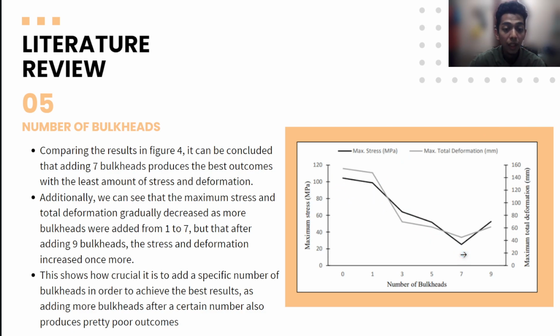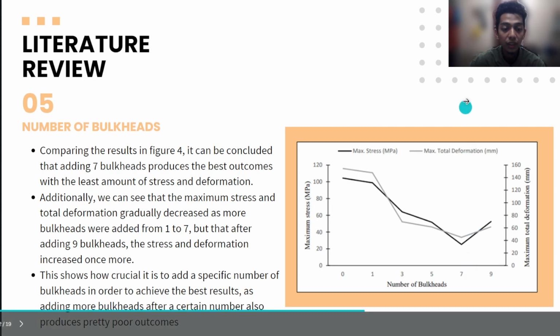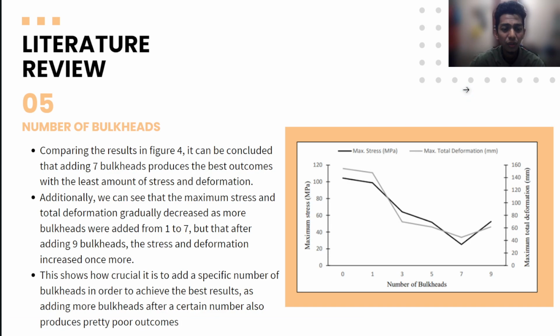But after adding 9 bulkheads, the stress and deformation increased once more. This shows how crucial it is to add a specific number of bulkheads in order to achieve the best result, as adding more bulkheads after a certain number also produces pretty poor outcomes.